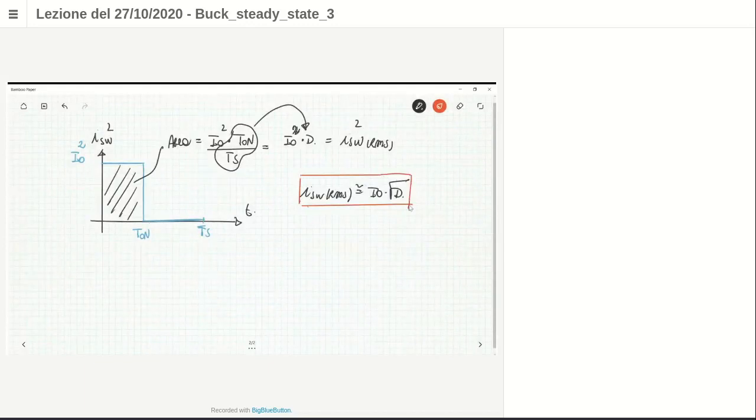Okay, so this is the root mean square value of the current through the switch that we should use when we want to compute the conduction loss of this MOSFET. Of course, when you want to get the maximum, you have to insert here the maximum duty cycle, and then you get the maximum current, okay, in order to get the maximum possible value in the worst case.